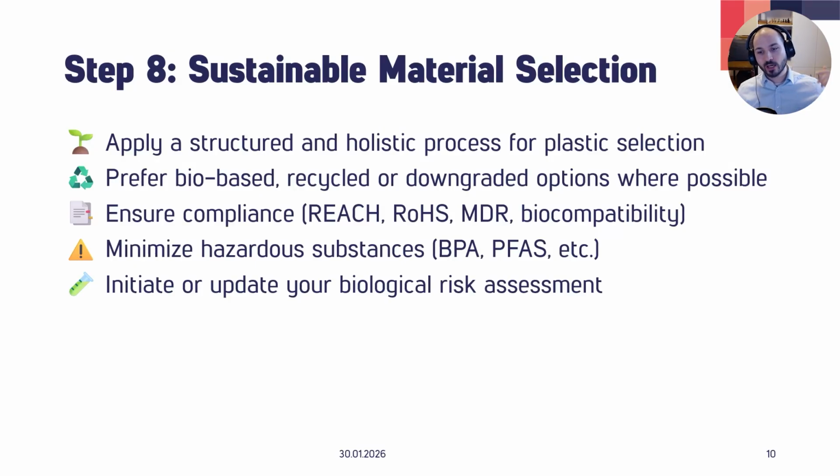The idea is here to balance technical, regulatory, and sustainability requirements against each other. I would prefer to use bio-based, recycled, or downgraded options, of course, where possible. Ensure compliance to REACH rules, biocompatibility, MDR, and minimize hazardous substances. So bisphenol A or PFAS should be reduced as much as possible, since those will get under regulatory scrutiny in the future, and they're also not future-proof. They can also cause some issues with biocompatibility.